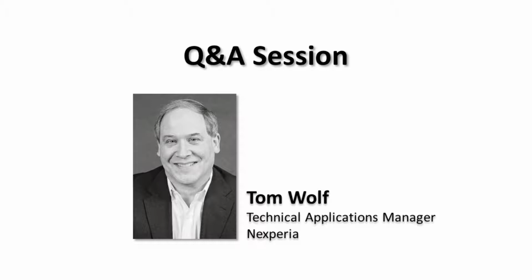Okay, what we're talking about here is Cauer models. We spoke about Foster models and Cauer models. The main difference between them is Foster is just inside the part itself. Cauer allows you to expand your simulation outside of the device itself. I get the heat out of my part, now it goes into the PCB and the heat sink or whatever.